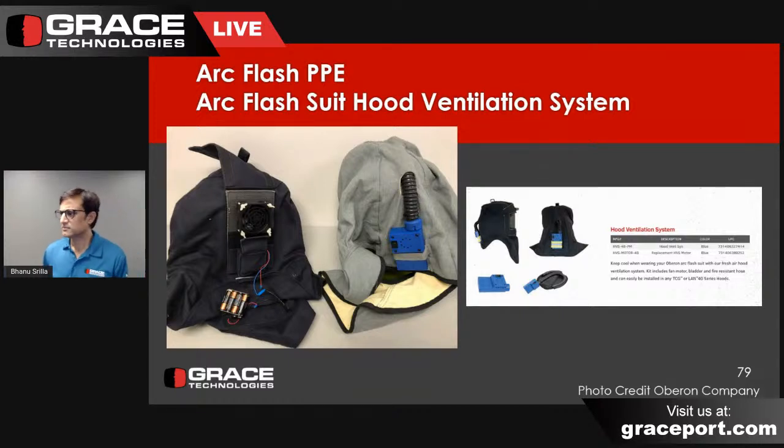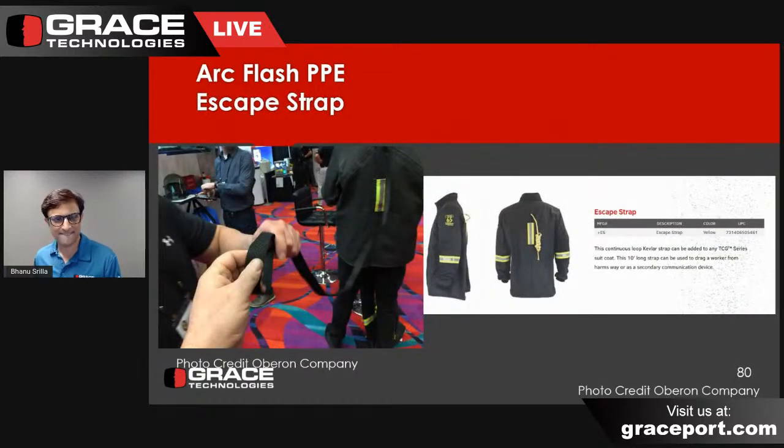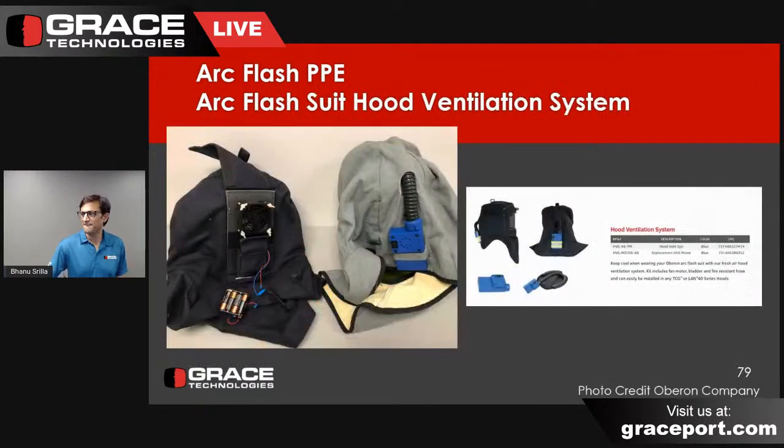So again, the hood ventilation systems: on the left, you'll see what I've seen too many times, which is a computer fan converted to a hood ventilation system. Right? First of all, get a hood ventilation system on your arc flash suits. You need to budget and update your PPE. The hood ventilation system is critical for the worker's comfort, brings oxygen to the front, and helps defog the lens. So I encourage you to spend the money and get a hood ventilation system, but get one that's industrial quality, like the one on the right, which is from Oberon Company.